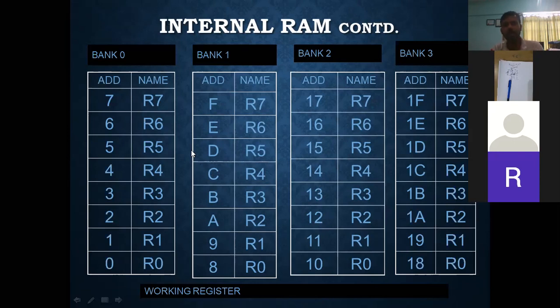Whenever you come back to college and do your laboratory, I'll show you that if we put a multimeter on pin number 9 when the switch is not connected, you will find a small amount of voltage. So it is still a DC one, but a very small amount of AC components are present in the DC, and that charges the capacitor.